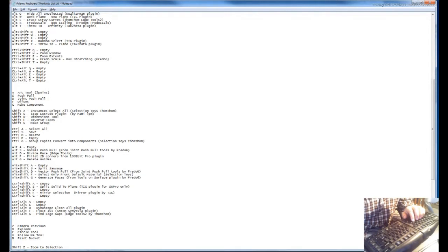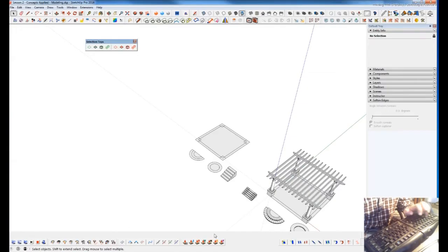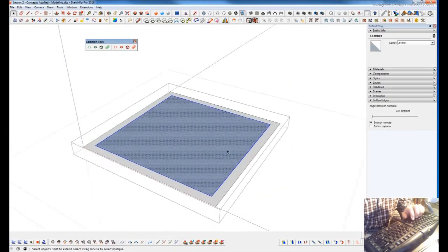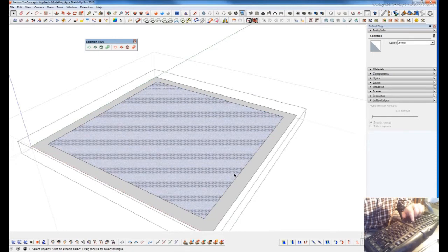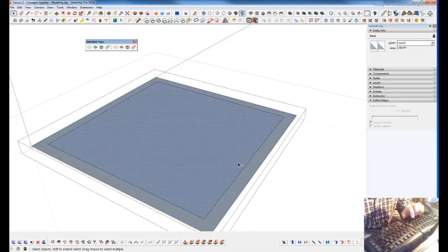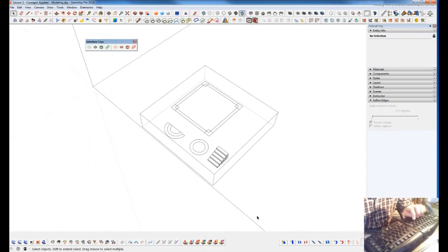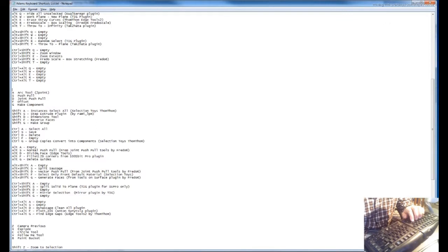Jump back here. So we did step extrude, dimension tool. I think might natively be D, and since I took D for joint push pull, I just switched it to Shift D. Reverse faces, Shift S or Shift F. I do that all the time. Very quickly, I can grab, as I'm modeling, Shift F is probably the easiest thing to find as a variation key. Pinky to shift and your finger's already on F. So you can very quickly switch faces, select them, flip them, and go through.